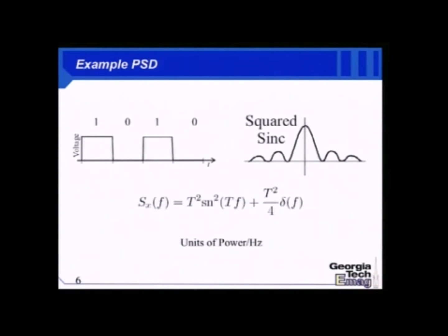So, if I wanted to, I could pick another signal. I could pick triangles instead of squares. One of the things, squares, it turns out, are lousy pulses for sending information. They're really easy to generate. You just put out a voltage of 1 or 0 or 1 or negative 1 to represent it. Very easy to generate electronically. Lousy from a spectrum point of view because the sinc function, its little spectral side lobes, take a very long time to die out.